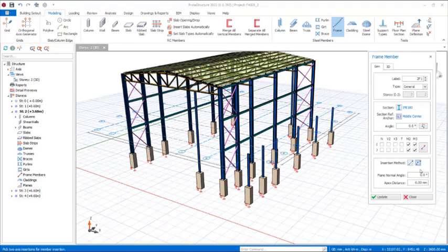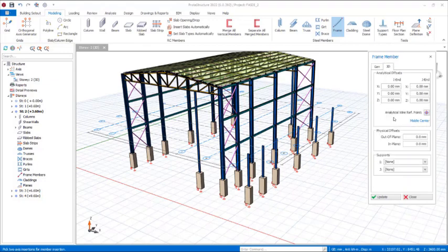So once you get that selected, you just have to come over here. The angle of rotations is going to be 90 degrees, and then we will have an apex distance to be 130. This apex distance can be edited later. All right, so if you come to the 3D sections, in these 3 sections you can see the analytical offset. All right, so if you want to offset the analytical line, you can use these provisions. For the sake of this lesson, we are not going to do that.